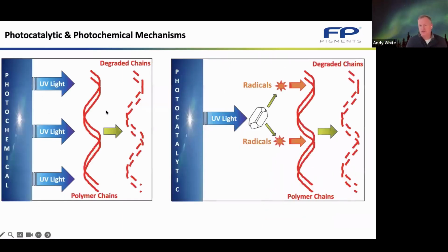Essentially, there's two things you have to consider when you're thinking about paint degradation. One is basically, is your polymer going to be durable enough? If the polymer isn't very durable, you're going to find that the polymer will break down. And this is often the case in very cheap alkyd paint, where the polymer breaks down, the effect of the TiO2 or anything else in there is minimal.